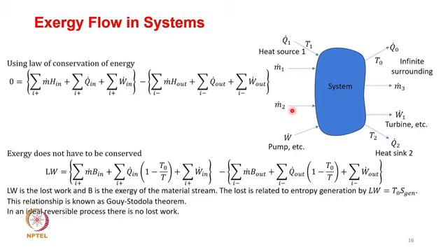So, it is a general process condition wherein you have almost all such scenarios accounted. So, by the law of conservation of energy, it is very clear that m dot times H in, Q in plus W in will be equal to m dot times H out, Q out, and W dot out. The dot indicates that it is a rate. So, this is the law of conservation of energy, and what is the exergy loss here? m times B in, fine. There is no B here, this is simply the conservation of energy.